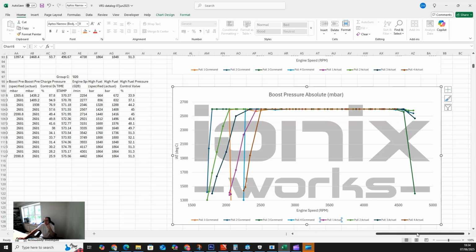So my next protocol here will be to move up to a 4-bar map sensor. Excuse me, I will get on to the guys in Top Gear Tuning and ask them to recalibrate for that 4-bar map sensor. God, the hiccups today are ridiculous. Excuse me. And then I will repeat this testing just to see exactly what is happening.